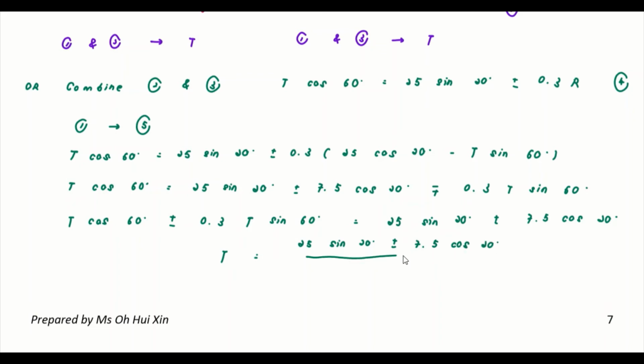then over cos 60, and also it's plus minus because I'm moving to the other side, then it becomes divide only, so the sign doesn't change. So you can imagine as if let's say this is plus, you move that, it's also plus, right? This is minus, you move over the other side, also plus. It's minus, sorry. Okay, so you can use your calculator to press the first time using plus, then after that you use minus, then you solve the other one. So you'll be able to get your two answers: 20.5 Newton in three significant figures and 6.26 in three